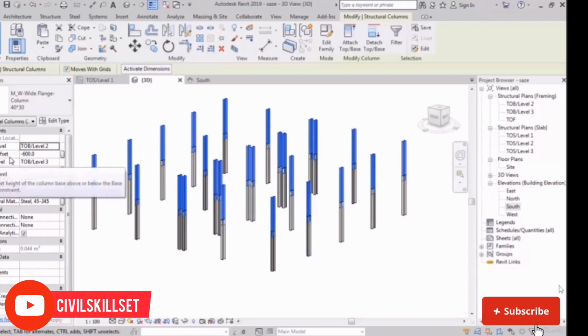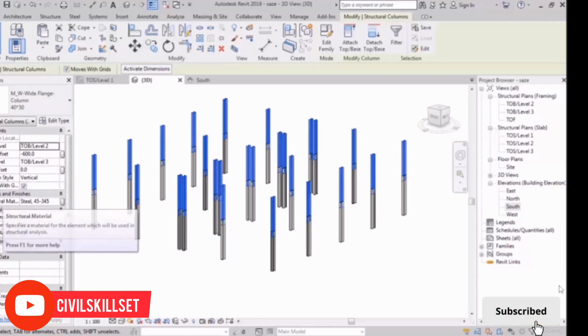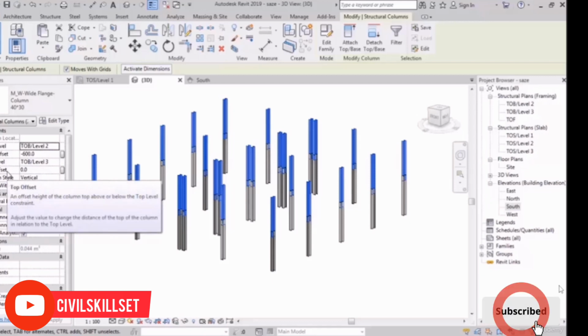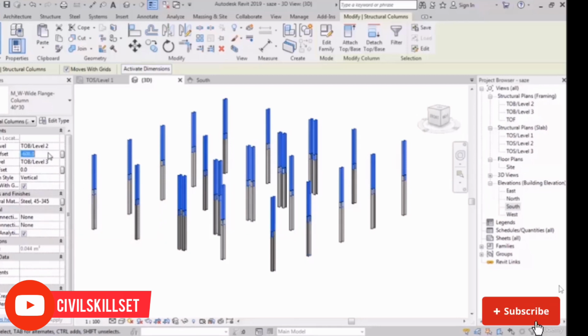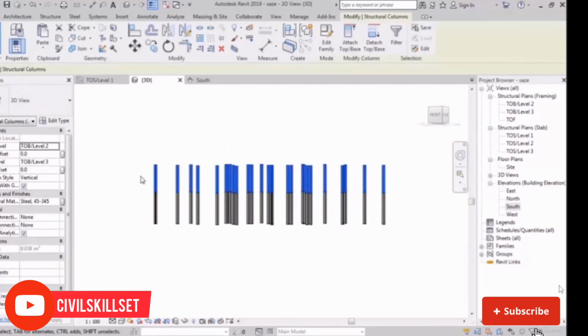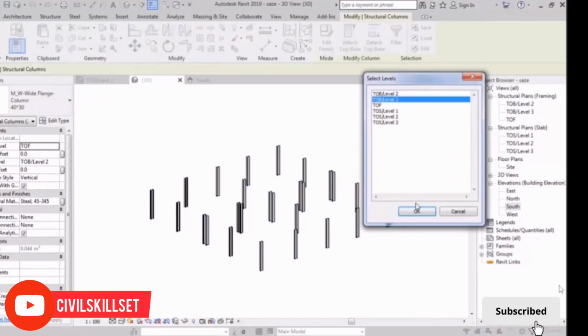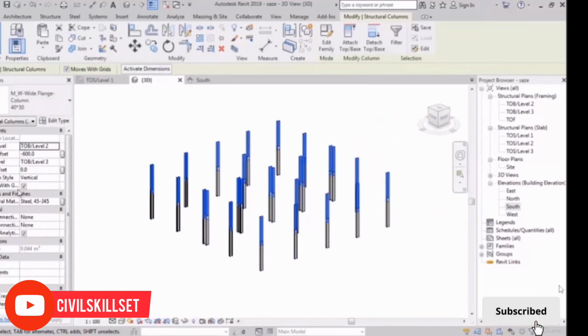Now, how can we delete that? We talked about it in the walls. We have something called base offset and top offset. I said in the walls, it's the same thing in columns. Base offset and top offset of the column should be 0, unless we set it ourselves based on a detail or a design. So while it's already selected, you can just change the base offset to 0. Let me do it again. I'll select it, copy, and paste, because they've reached 3. I paste it in 3. While it's already selected, I check the base offset. It has one, so I'll change it to 0. And now the height is okay.